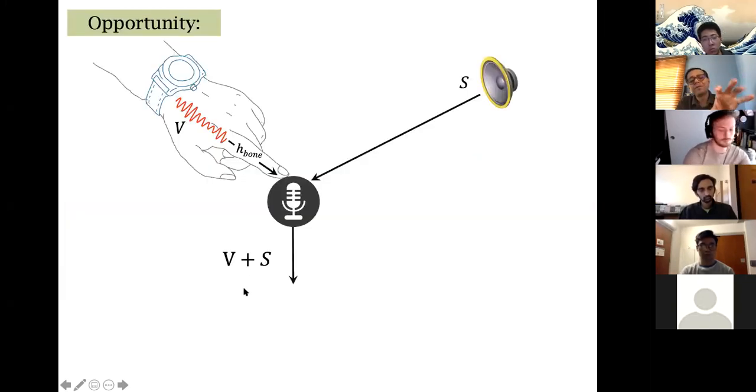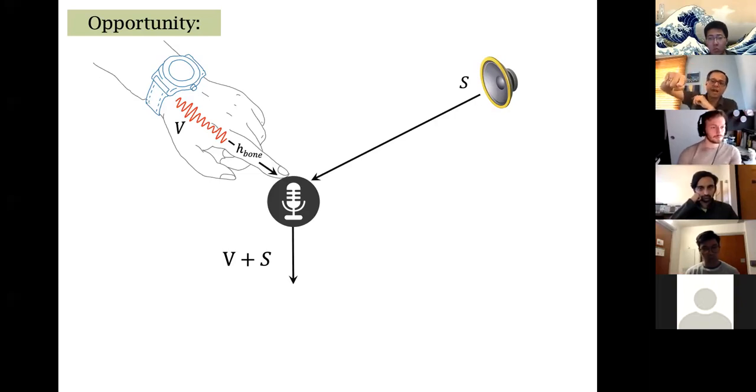Now, one of the issues when we were doing some of this research was that with the accelerometer, you were getting around 400 bits per second, simply because the accelerometer bandwidth is pretty low. So how can we increase the bandwidth? The answer was, why don't we look at the microphone? Because the microphone's bandwidth is 20 kilohertz easily, and the vibration motor's bandwidth was 16 kilohertz. Great, let's use the microphone. And the point was, we'll touch the microphone with our smartwatch vibrating.